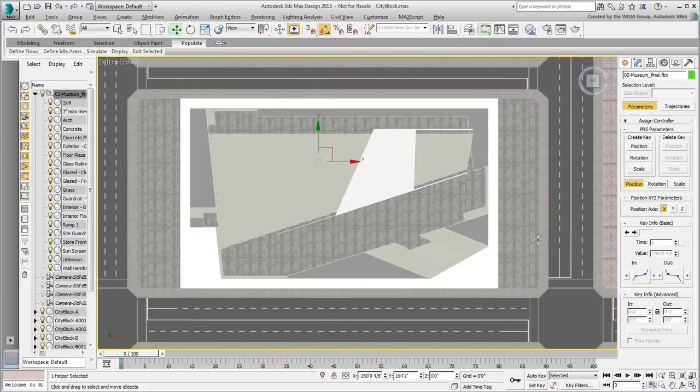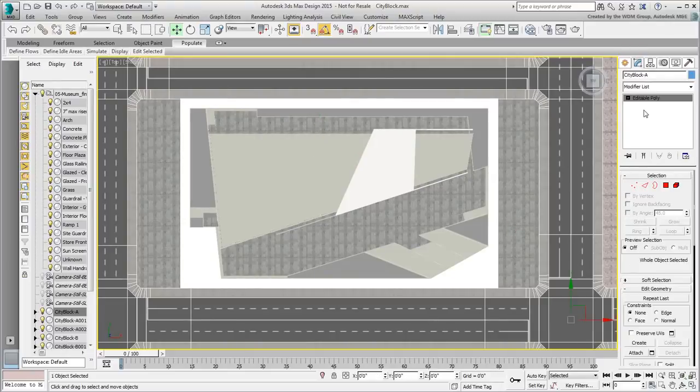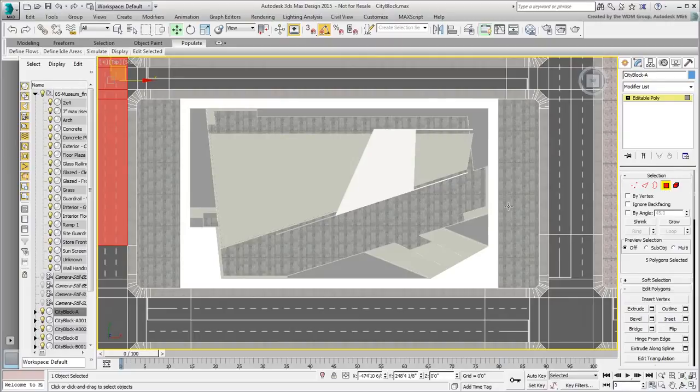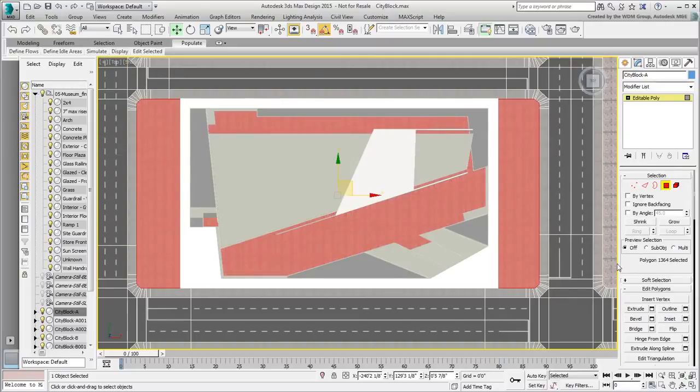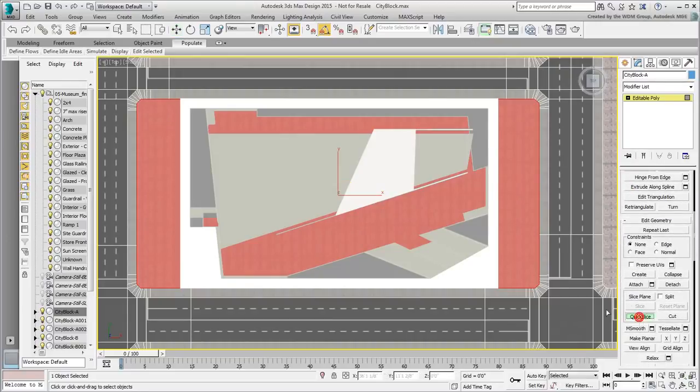In the top view, go ahead and select the existing ground surface and go to the Modify panel. Enter Polygon mode and then select the construction lot. You need 2 vertical cuts to subdivide this surface in order to get rid of the centerpiece. Use the Quick Slice tool to specify 2 points defining a vertical line along the left edge of the plaza.